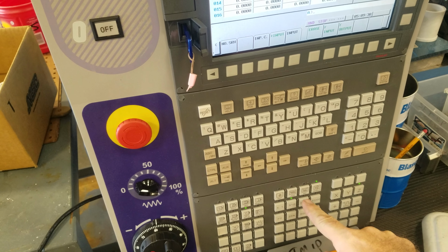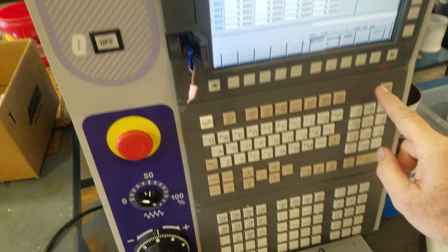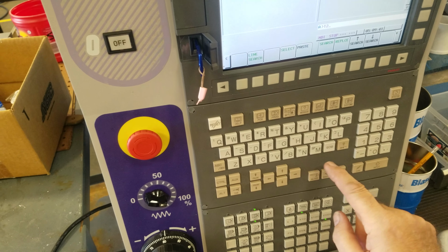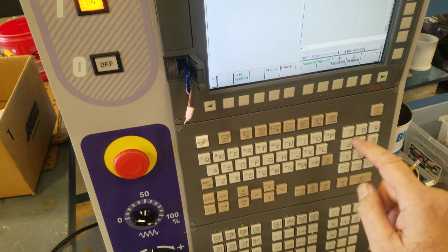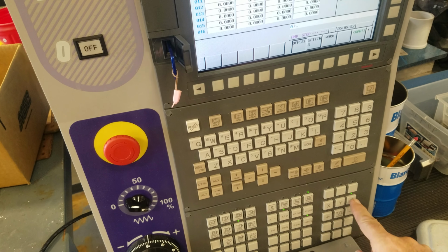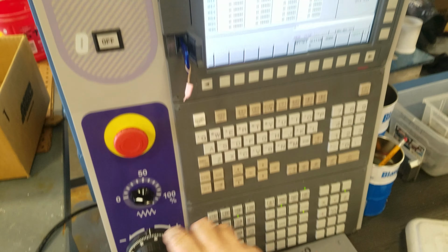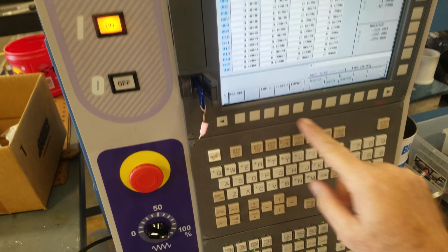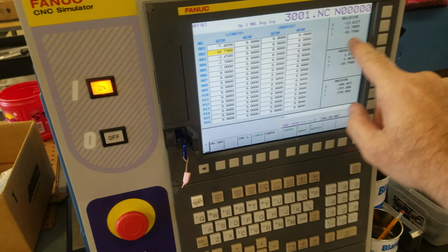So I will go back to MDI, program, this program, then I'll go change my tool again. I go T2, M6, end of block input, cycle start, right? And then I'll go back to my offset page, go down to my next tool, handle jog Z, bigger number, bring that one down, 1,000th when I get closer. Looks good. Operator screen. I'm going to do Z input coordinate. Matches. Okay.